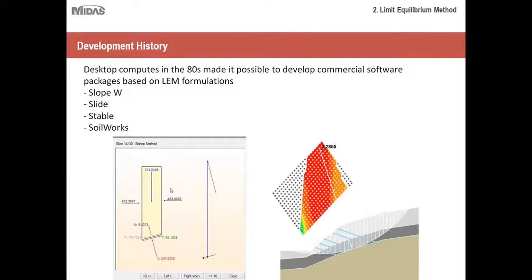And in fact, you don't even have to calculate the interslice forces or the forces acting on your slices by yourself. A computer program will do all of that for you. It'll create a series of arctangents, and it'll perform the analysis over and over again based on this grid range. It'll isolate the minimum factor of safety for you. So something that would have taken half a day or maybe even 2 days for one engineer to do can actually be done within a matter of minutes by this computer program.